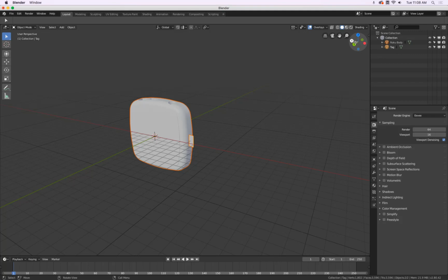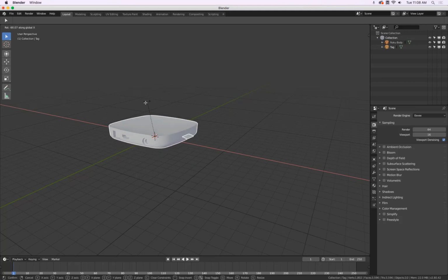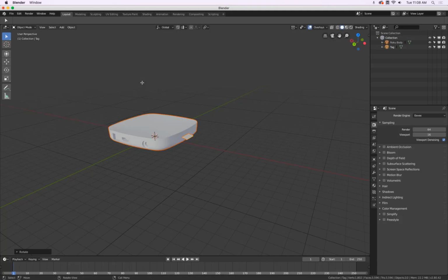And we know by the red that it is X. So we can press R for rotate. We can press X for the X-axis. You see now it only rotates around the X-axis. And when I move this horizontally and pay attention to the upper left corner, it tells me that's negative 90 in this case. So minus 90, enter, there we're done.